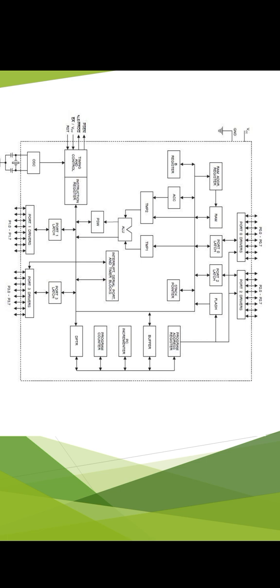INT0 and INT1 are interrupt pins. There are 2 interrupt pins. These are 2 external interrupts, that are active low. VCC and GND are the voltage supply. This VCC voltage is a 5 volt supply, and the ground connection. These are the 2 pins, voltage pin and ground pin.